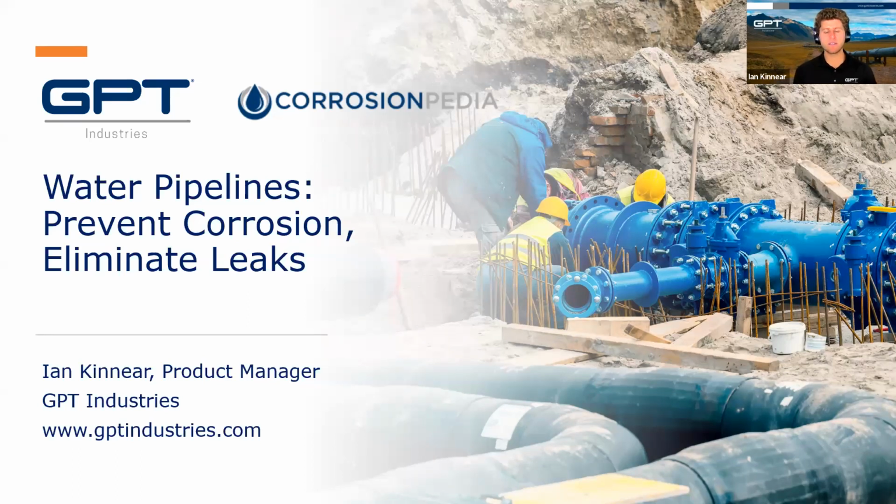As we know, isolation is commonly used in water applications, right? And it's critical that when a flange isolation kit is used, it performs both its job of isolation and sealing, which is what leads us to the prevention of corrosion in the lines and eliminates any lost products in the form of leaks or whatever it may be.